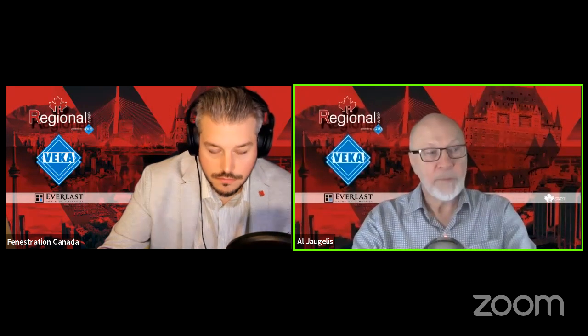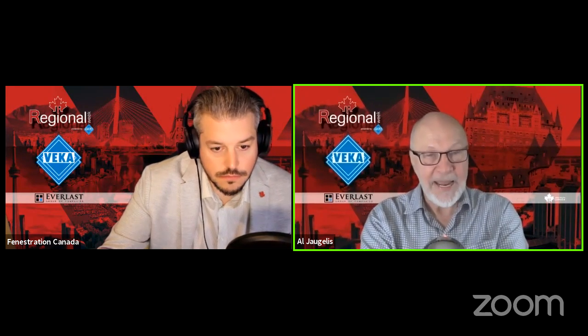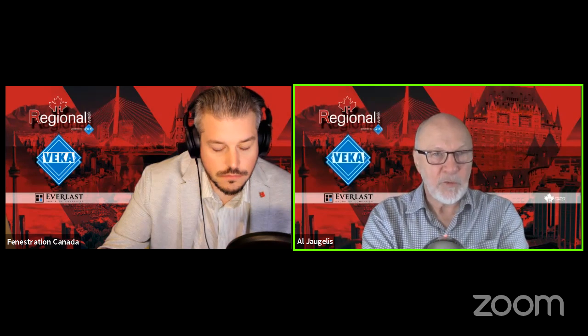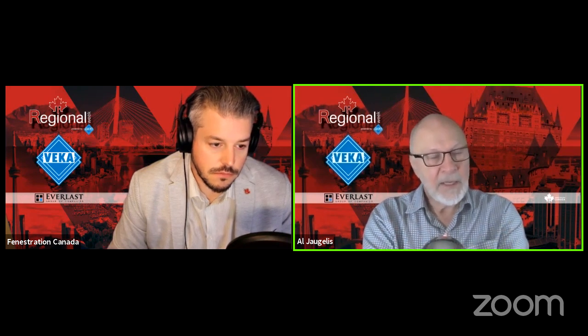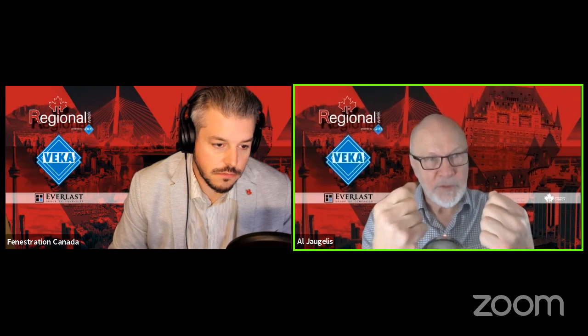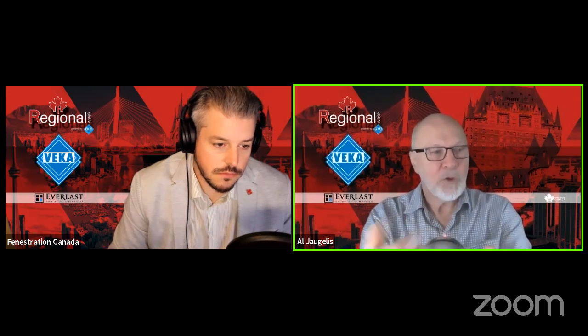If it is a new subdivision that would be in open terrain today, but when it's built out will be rough terrain, there's a couple of ways to look at that. In terms of design wind loads, those use a 1 in 50 return period. In terms of the driving rain wind pressures for small buildings, it's a 1 in 5 year return period climate data. So potentially your most serious water event could occur.